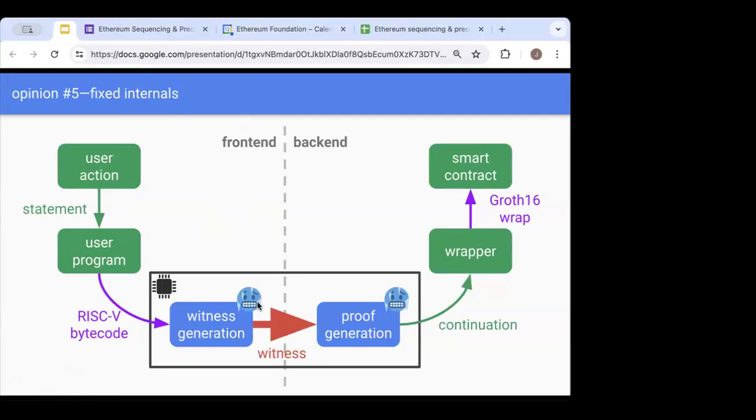Yes. So the recursion actually comes into two places. One is internal to the chip. You have these cycles that come in, you have these little chunks, and you have to glue everything together. So there's some amount of recursion in the chip. But the other cool thing is that there can be recursion that is cross-chip, and that allows you to scale horizontally. If each chip can only run the RISC-V CPU at, let's say, 10 megahertz, but you really want to run a system at 1 gigahertz, you can basically have 100 chips that are horizontally scaled, and they all stitch together with these continuations that they produce.